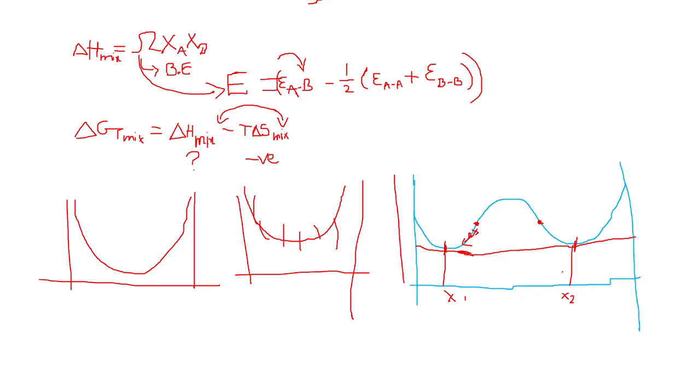So that is the reason why at normal homogeneous coolings, you will have pearlite, right? But that is not always the case when we try to cool the steel, carbon steels, right? The low carbon steels. And the reason why is because of the undercooling.